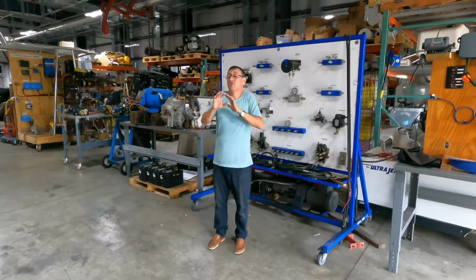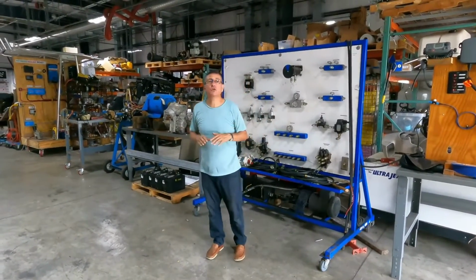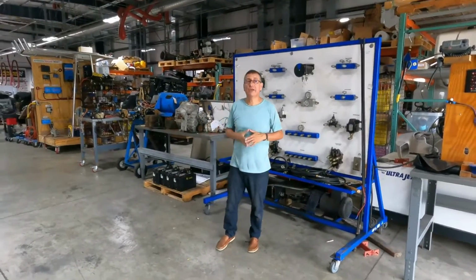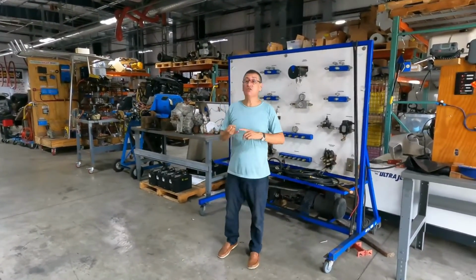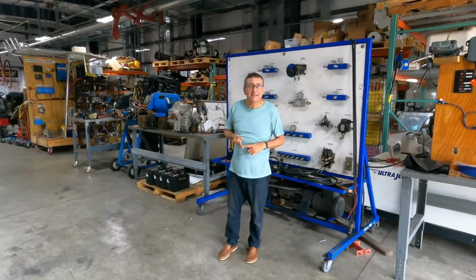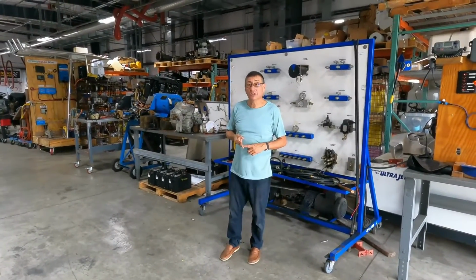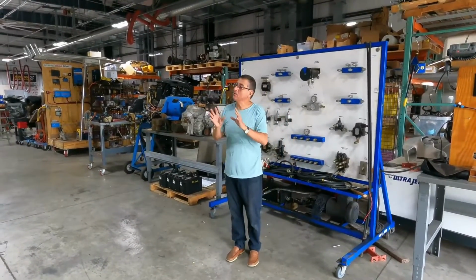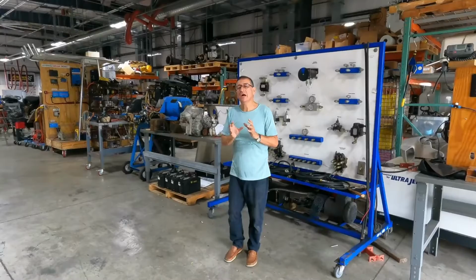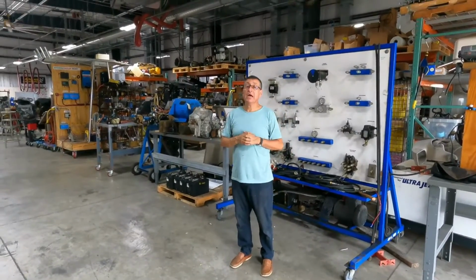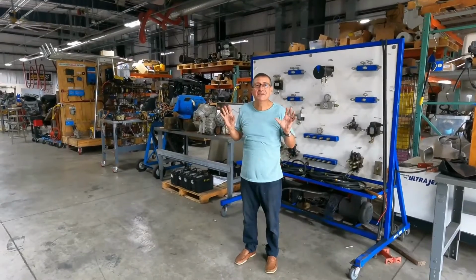What happens if for some reason my generators do not respond? I don't have generators. I am in the middle of the ocean. They're using an inverter. Right now I don't have anchor, I don't have windlass, I don't have anything. Is that good? No. Okay. This is why those central hydraulic units are created with redundancy, with backup. And the backup is mechanic.